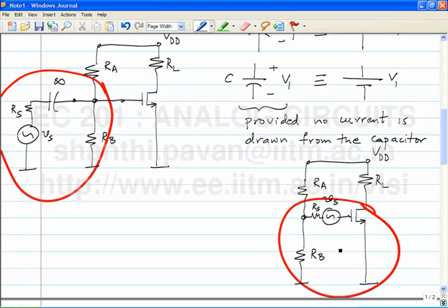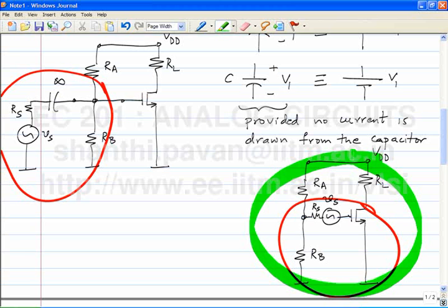So you don't have the freedom, for example, to access. If you had both the terminals, sure, you could stick it in series with the gate, as somebody suggested. But in practice, many sources will not allow you to have that. The two terminals floating like this, one will automatically be ground. So while the one shown here, there is nothing fundamentally wrong with it. However, there is a practical disadvantage that both the terminals of the source need to be accessible if you want to stick it in series with the gate.